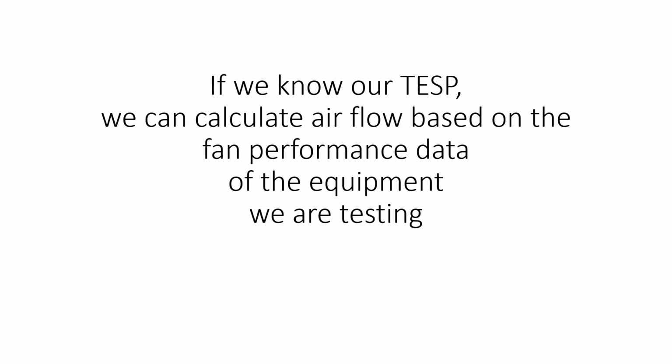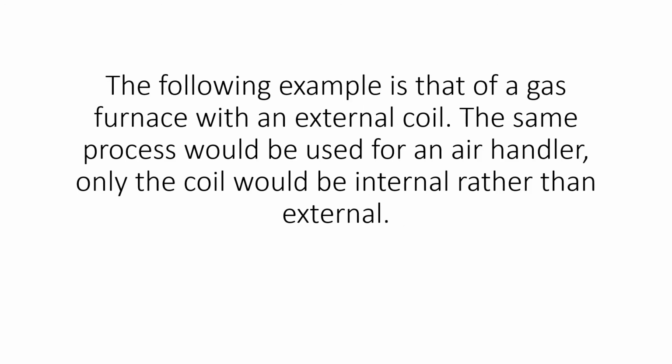If we know our total external static pressure, then we can calculate airflow based on the fan performance data of the equipment that we are testing. The following example is that of a gas furnace with an external coil. The same process would be used for an air handler or even a package unit for that matter, only the coil would be internal to our equipment rather than external, just like we discussed in the previous drawing.